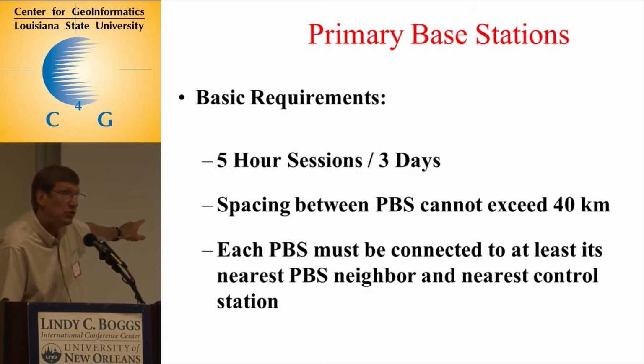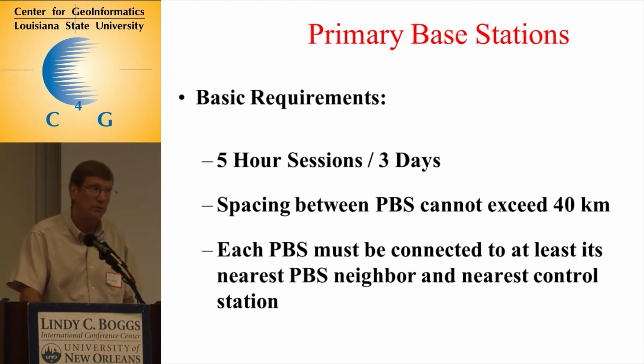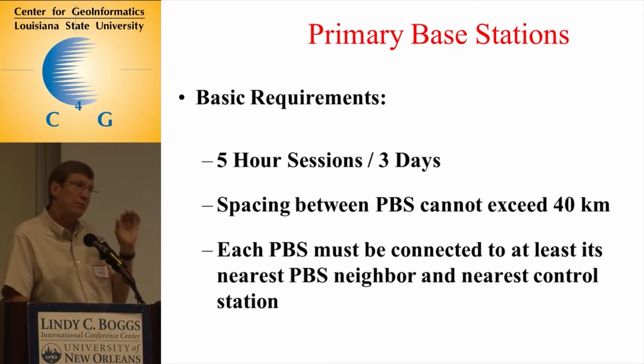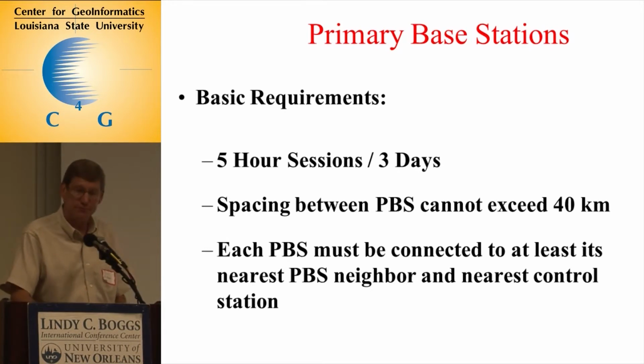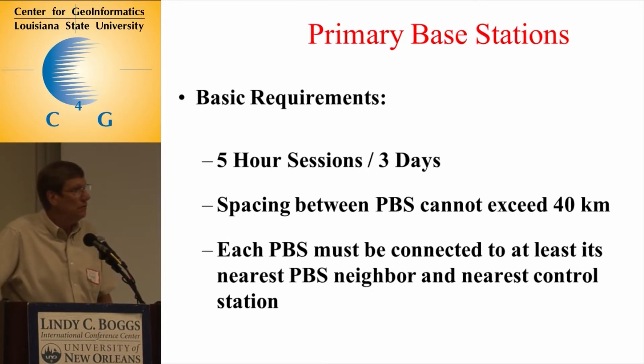Now, each one of these primary base stations needs to be connected to its nearest neighbor. So when you've got a primary base station and you go to your next one, it's 40 kilometers away, you need a direct connection. You need to be occupying them at the same time.